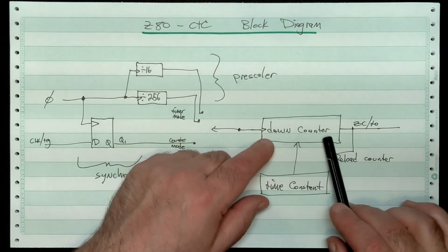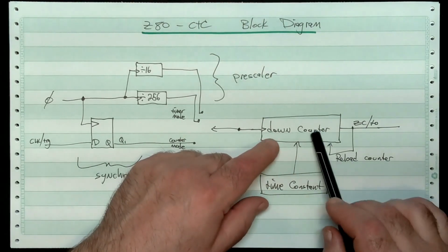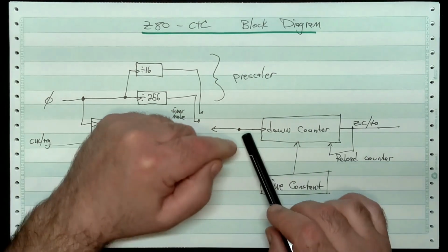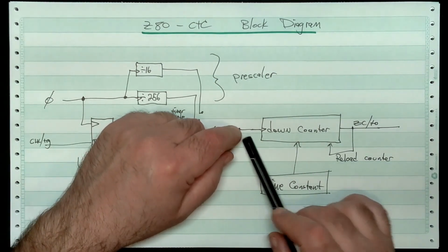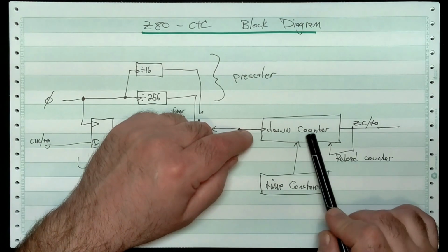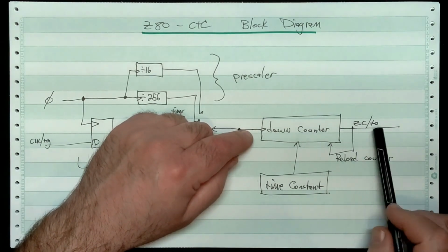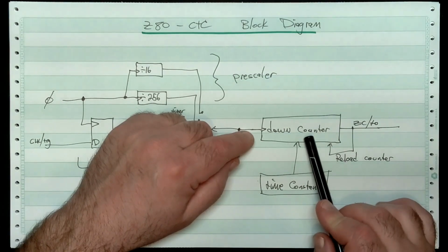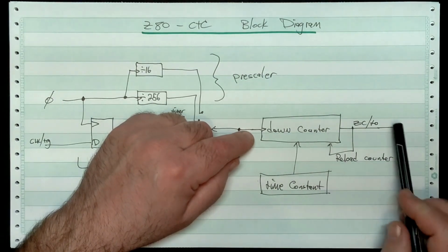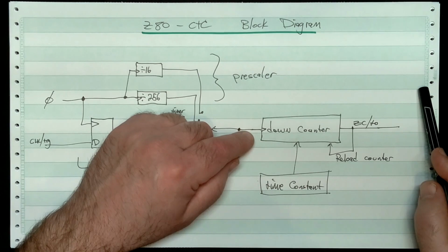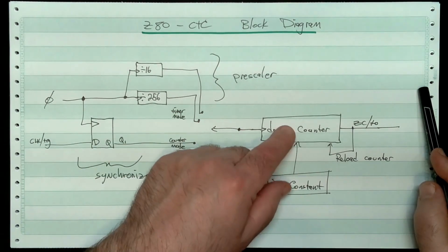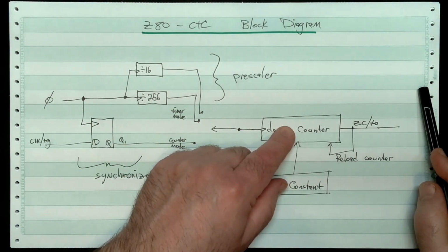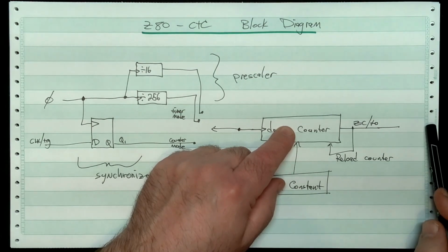So if this thing is currently 0, it will have reloaded itself with a 2. All right. So this is going to come along at 100 times a second. Current value is 2. There's a pulse. It goes to 1. It's not 0, so this is low. It pulses again. This was a 1, it then becomes a 0. This thing goes to a 1 now. At that point, the 2 gets put back in here. This thing goes back low again.